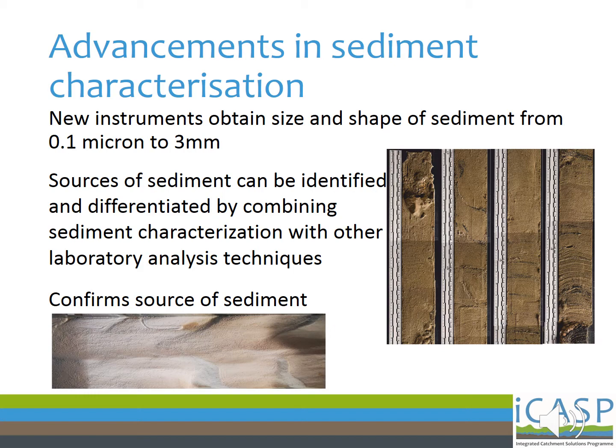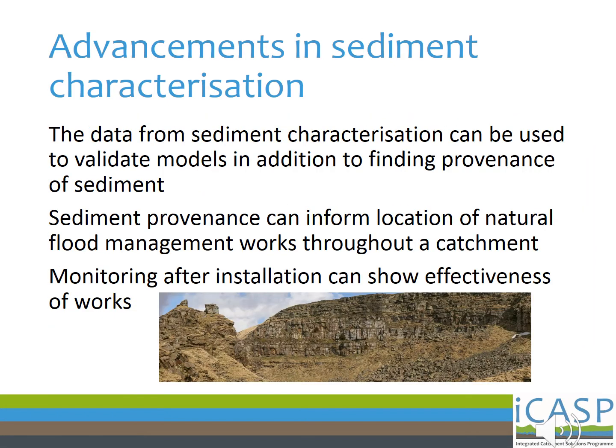For scale, there are 1,000 microns in 1 mm, which shows a huge range of sediment size that can now be analysed. By comparing the minerality of a sediment to the geological bedrock maps, you can surmise whether the sediment is from that area, or if it was eroded upstream and has been deposited in that site. The data from sediment characterisation can then be used to validate models for erosional zones, flood risk, and other hazards.